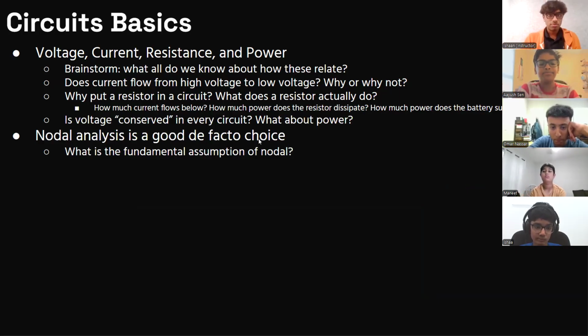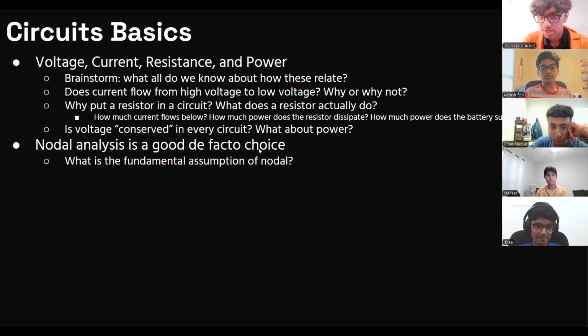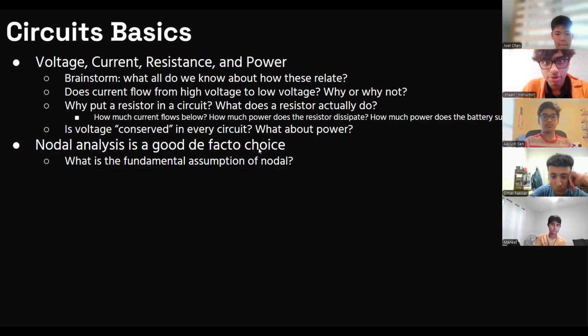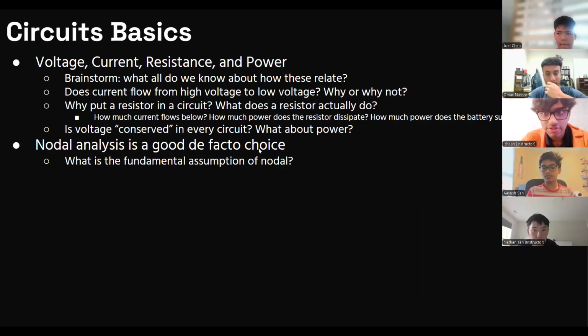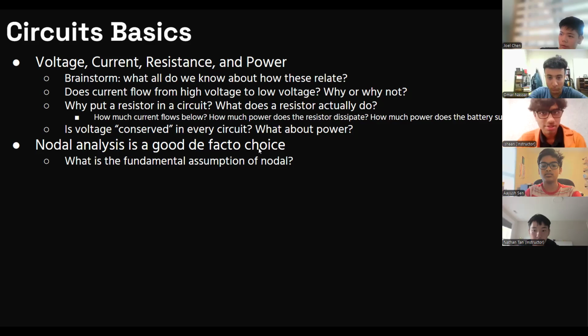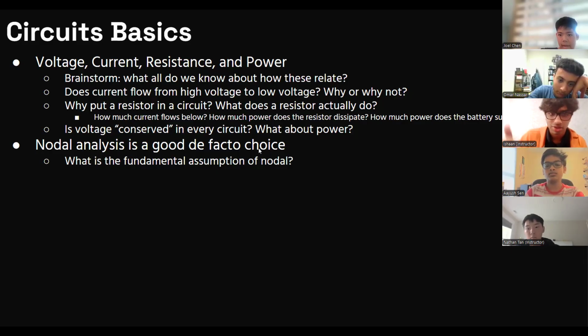And so now this is the biggest moral of the day. Nodal analysis should be your de facto choice for circuit analysis all the time. I know there's a lot of push to use mesh, and mesh is fine if there's shortcuts that allow you to make your systems of equations easier with mesh. However, these simulation tools that we'll talk about, LTspice, for example, operate with nodal analysis. Nodal analysis is the minimal way of analyzing a circuit. And there's graph theory reasons you can think about for that, and very elegant mathematical reasons for why it is the minimal way to analyze a circuit. But nodal should be your go-to approach when you're presented with a circuit to look at.